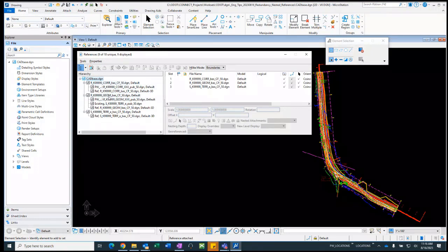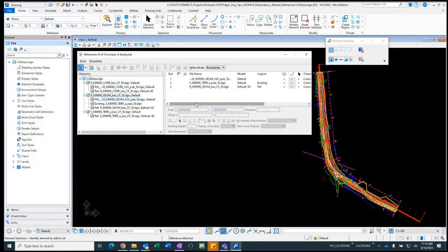This is a case where I mentioned this earlier. If you see that a designer or surveyor has left other information attached to their container file, there's no reason to attach a published terrain to a geometry container file. You need to talk to the designer or the surveyor and ask them to either detach the reference, or they could set that reference attachment to be ignored when live nesting.